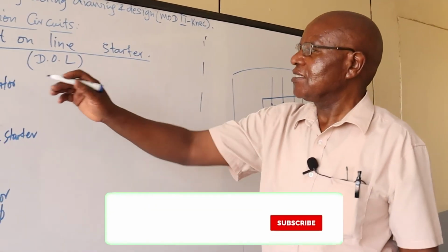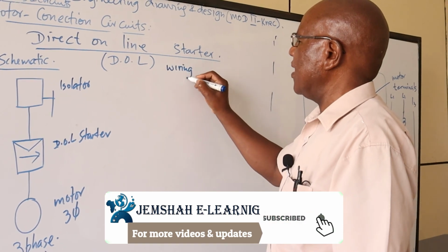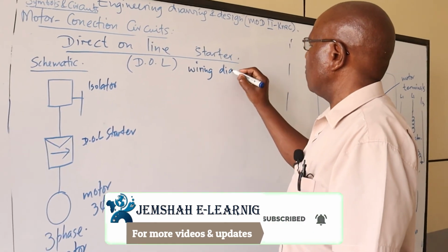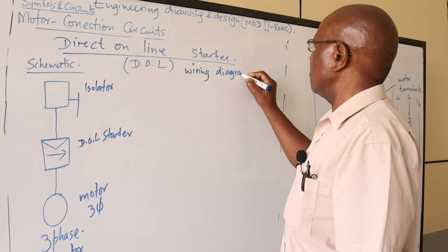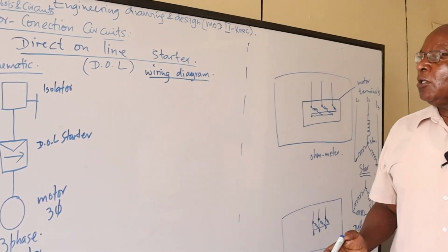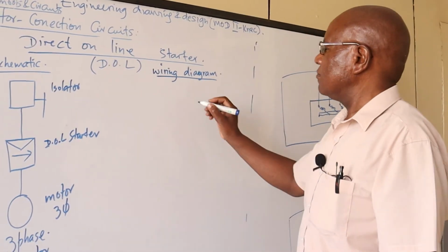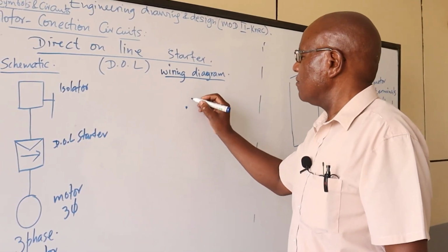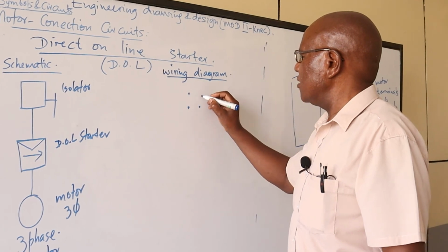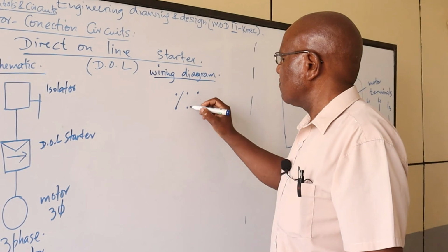So now that is the schematic. Now here, I can produce the wiring diagram. Now much of your NEC examinations, they will be looking for the wiring diagrams. So in this case here, I've got the isolator. In the isolator, I need to isolate the three phases.